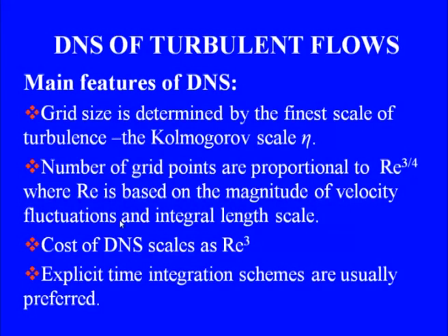So, any increase in the Reynolds number would lead to a tremendous increase in the cost of performing a direct numerical simulation. We require in direct numerical simulation a very accurate time history, and that is the reason why we can overcome the stability requirements rather easily; they are met automatically. So, explicit time integration schemes are usually preferred in direct numerical simulation.